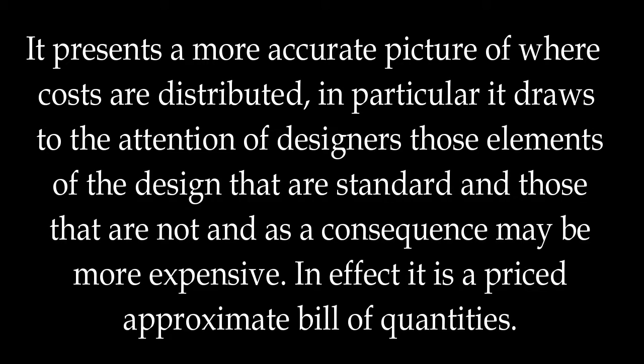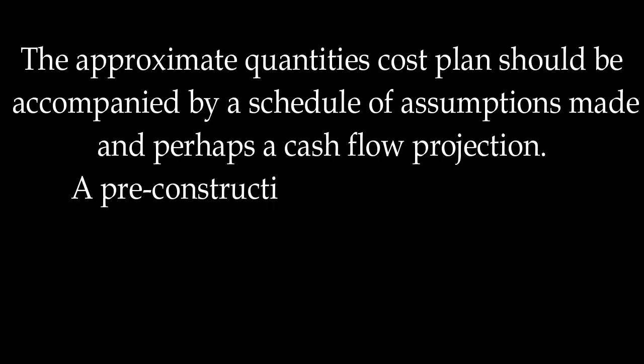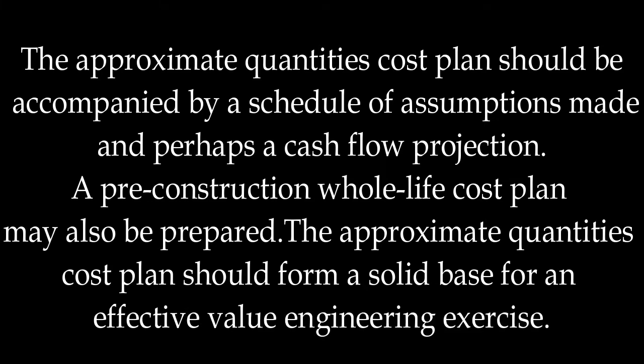In particular, it draws to the attention of designers those elements of the design that are standard and those that are not, and as a consequence may be more expensive. In effect, it is a priced approximate bill of quantities. The Approximate Quantities Cost Plan should be accompanied by a schedule of assumptions made and perhaps a cash flow projection. A pre-construction whole life cost plan may also be prepared.